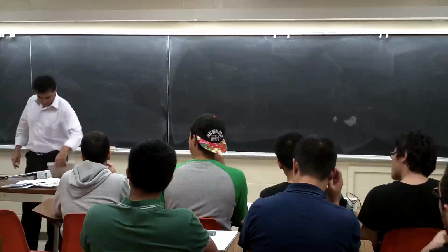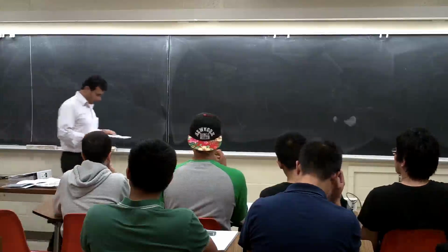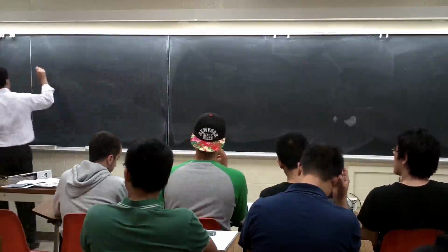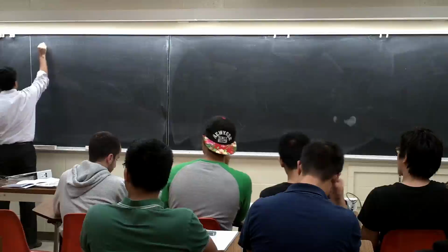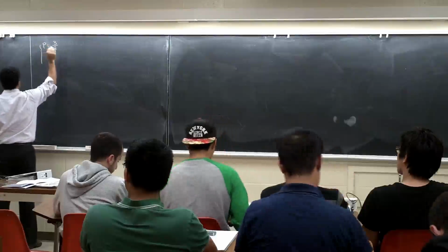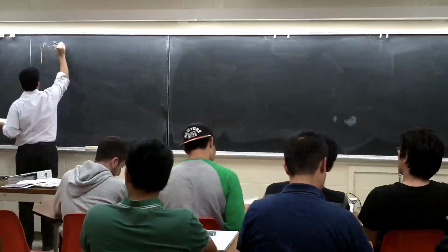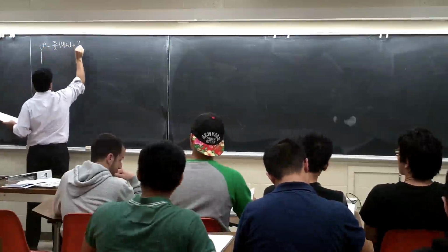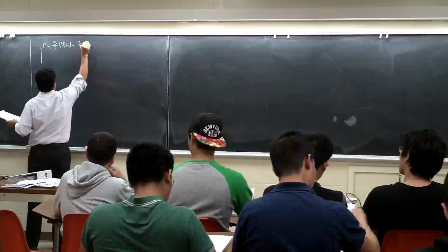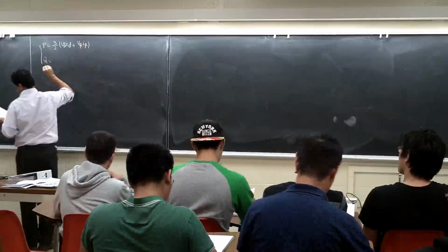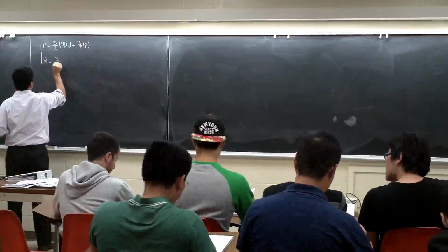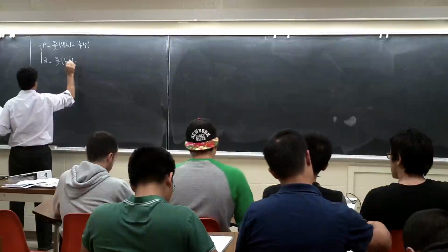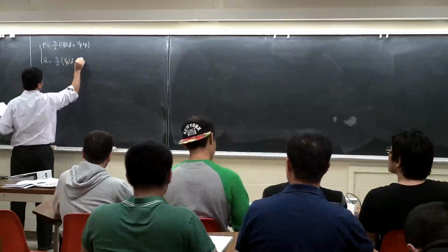Now, let's go back to where we were. The last thing I finished, if you remember, we said in a 3-phase DQ system, P is going to be 3/2 times (VD ID plus VQ IQ), and Q is 3/2 times (VQ ID minus VD IQ).